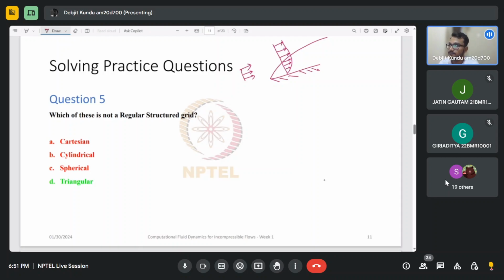So you can see that in this profile, in this entire distance, let's say this is from y equal to 0 at the wall to, let's say, y equal to some L at the top, and the boundary layer thickness, we will call it delta. Now in between 0 and delta, there are huge velocity gradients. So the velocity changes over here. And above delta, there are no more gradients involved. So this is basically a uniform flow from this point to this point.